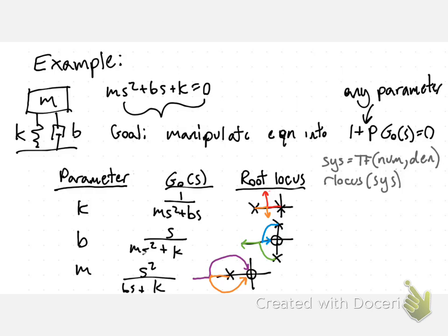So if we have a very small mass, we end up with a system that has somewhat strange properties, but then as we increase that mass, our system will either be overdamped, and then once it gets small, as it gets larger, it'll start to become underdamped, and then the larger it gets, the slower our settling time is, because the greater our tau value is.